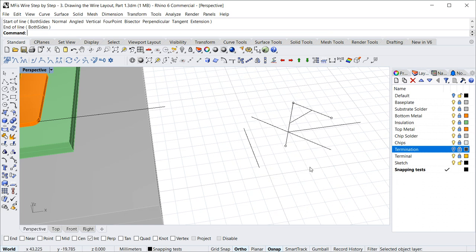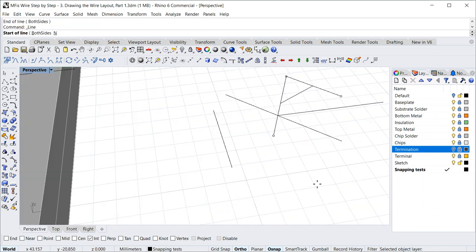It can snap to this. Also, when you draw a line just from somewhere and you are using orthogonal mode, then this restricts the direction, and this restricted direction will snap to the intersection with other objects. This is very useful. I often use this. As soon as you turn off orthogonal by holding the shift key, it will not snap.